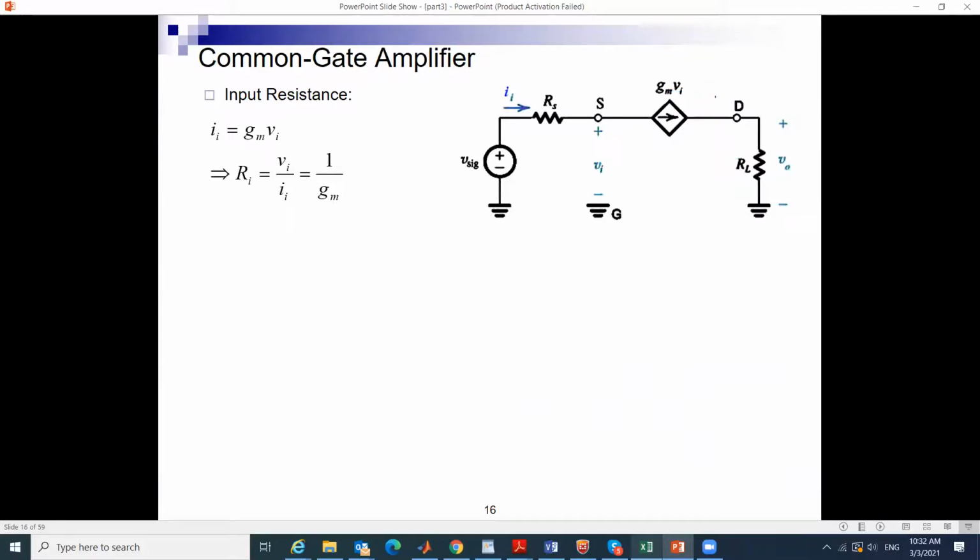So for the effective model for this amplifier, In is coming into Vn. So I can easily express my Rn. It is Vn over In, but what is In? It is GmVn. So directly the input resistor comes out as 1 over Gm.